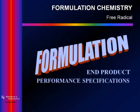Whether a company formulates its own coatings or has a formulator supply the material, the first question to address is, what are the desired properties of the end product and the process parameters during manufacturing? The product properties determine the formulation, but the formulation used to achieve those properties affect the process parameters, such as the viscosity and cure speed. Thus, the balance between the properties and the process parameters must be kept in mind during the development of a formulation. The next 4 slides summarize the materials used in a formulation, and the general effect each has on the final properties.